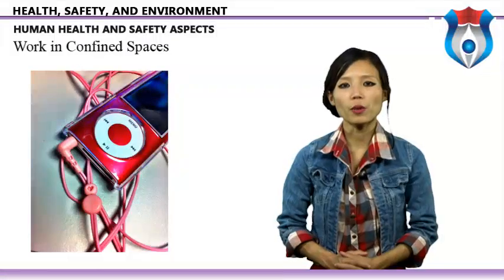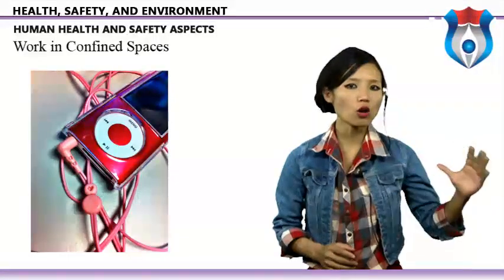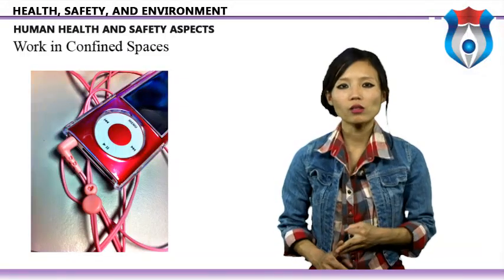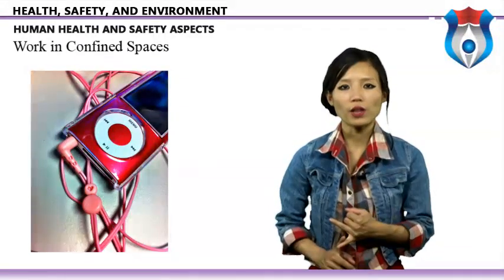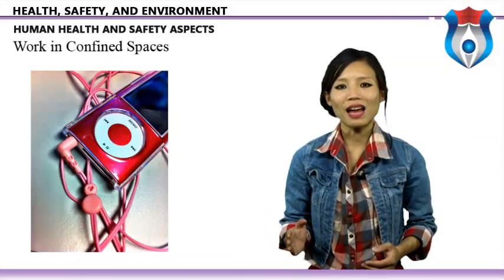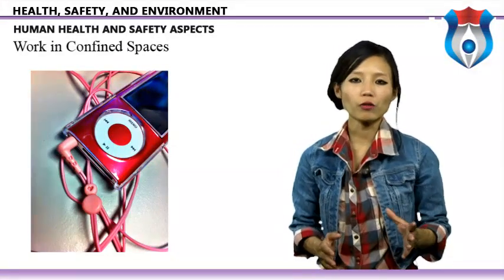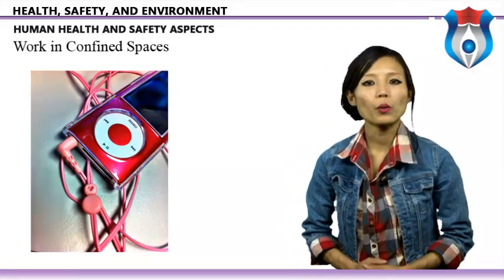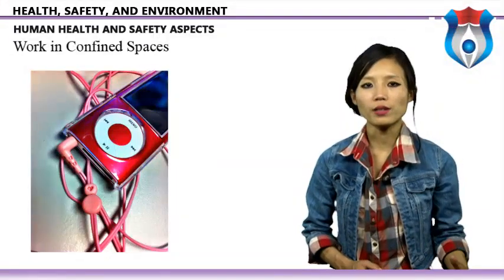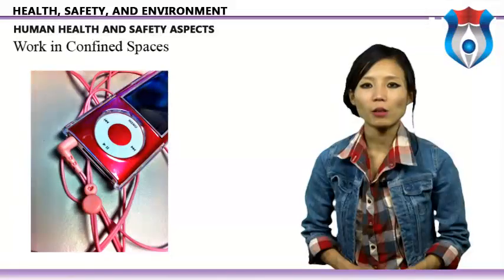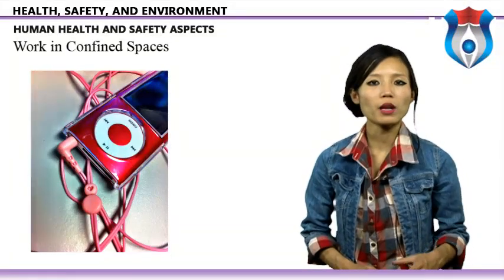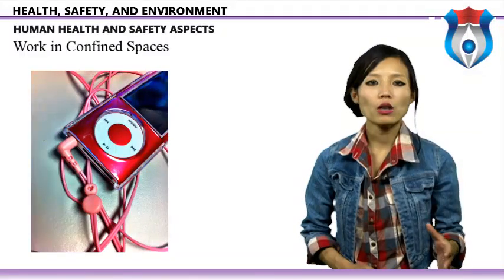Work in confined spaces. Prior to entry and occupancy, all confined spaces, for example tanks, sumps, vessels, sewers and excavations, must be tested for the presence of toxic, flammable and explosive gases or vapors and for the lack of oxygen. Adequate ventilation must be provided before entry and during occupancy of these spaces. Personnel must use air-supplied respirators when working in confined spaces which may become contaminated or deficient in oxygen during the period of occupancy.